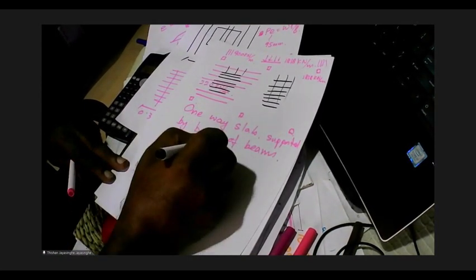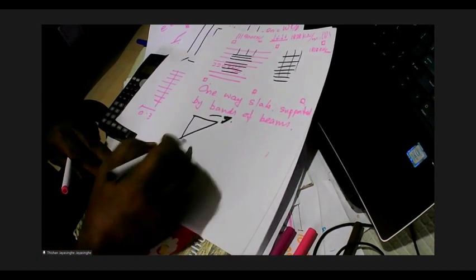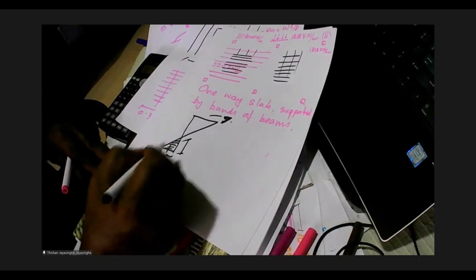So this may be about 5, this may be about 4, this may be about 7, this may be about 4. And if the allowable is 2, that is exceeded, which means the section is cracked. From this you can find the depth of this one, and from that you can find the force.